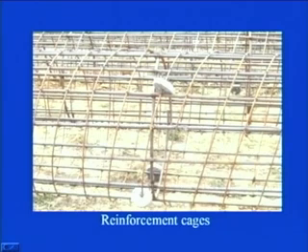Then you can see here a particular reinforcement cage lying. These are longitudinal reinforcement, this is the ring which is your lateral reinforcement, and these are your ties to bind these vertical bars in position. Then you can see there is a slab, sort of cylindrical kind of thing with a hole in between.